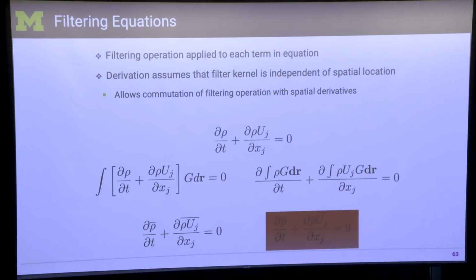This is the most confusing part about LES. You go through all these steps in theory, and you derive all these equations, and in the end, you get the exact same equation that you started with. Okay? Only for continuity. It doesn't hold for the other one. But it's important to remember this. The G factor, the factor that you use for the convolution, goes away. It's gone. So the notion of what is filtered with is not there in the filtered governing equations.